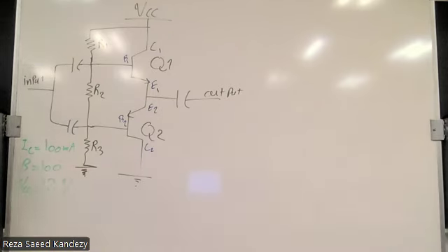But we all know if we want to have a proper performance, when we talk about transistors, BJTs and MOSFETs, we need to have a proper and strong bias, to make sure that we do not leave, like for BJT, the active mode and get to the saturation mode where we don't have any control over the gain. Are we good so far?